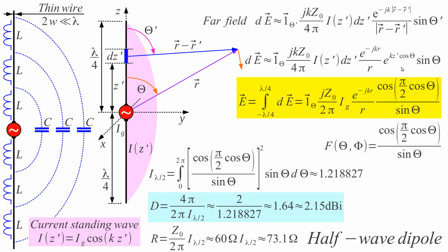The solution of the integral itself has sine squared in the denominator, but multiplied by this sine, I only have one sine in the denominator. Of course, j here, this is a complex exponent function with j missing up here. So the radiation pattern of my antenna is actually cosine of pi half times cosine theta divided by sine theta. This is the new radiation pattern, which is nothing special really. It doesn't differ much from the sine theta we had before.